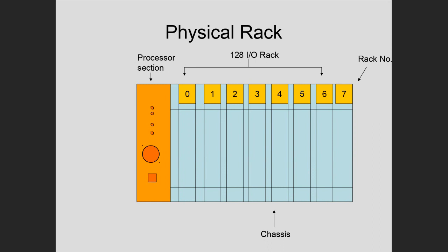So you'll see that when we talk about bit positions, or we talk about naming or numbering a row of a truth table, or an input-output module, we always start our count with 0. So 0 through 7, there's 8 modules here, and each module will have, for this particular setup, 16 connection points where I can connect a switch, or I can connect some kind of device I want to control. So that's where the 128 comes from. If you take 8 divided into 128, you'll get the 16 that I'm referring to.